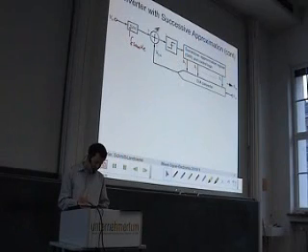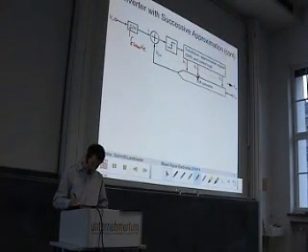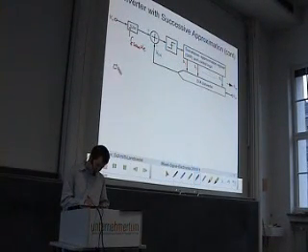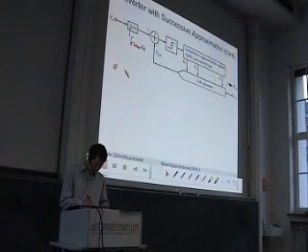We compare it again against the input signal, and according to the result, we set or reset the bit of this DAC. So the interesting thing is that the basic building block of this successive approximation ADC is a DAC. So the core component is a digital to analog converter.